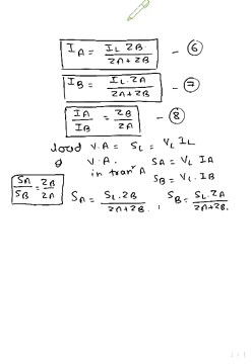Again, SA upon SB is equal to ZB upon ZA. So load sharing is inversely proportional to the impedance. These equations help us find the load VA, and the VA rating of transformer A and transformer B, and also how much load is shared by each transformer.